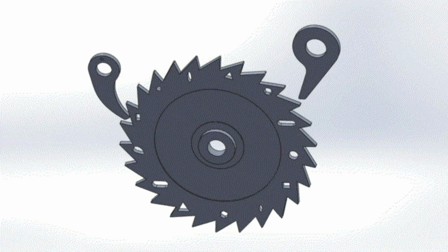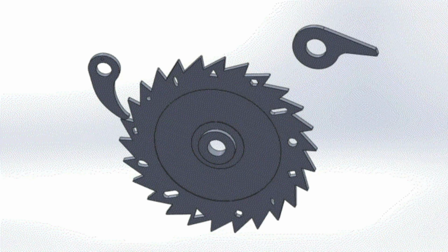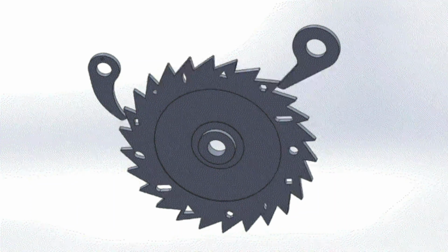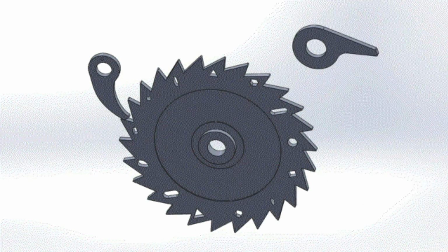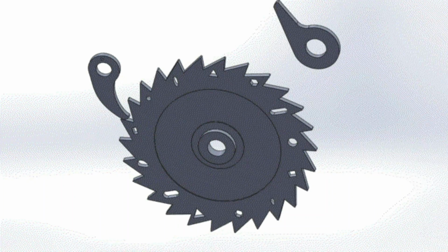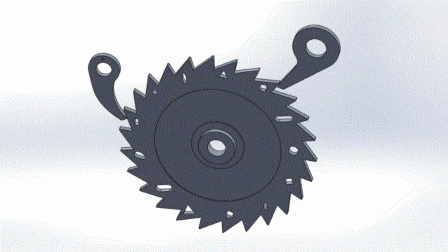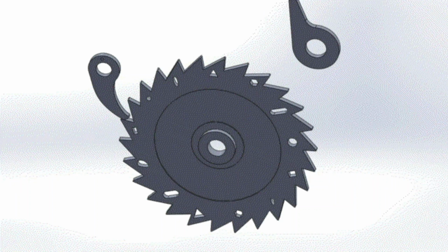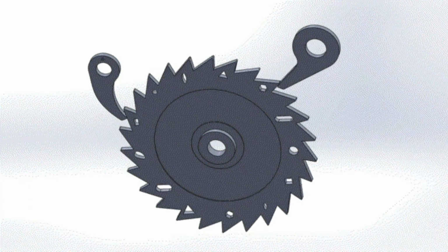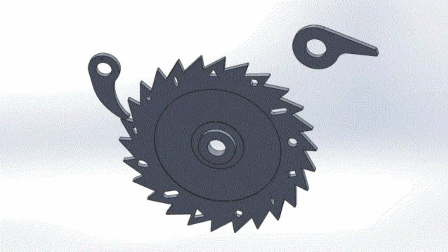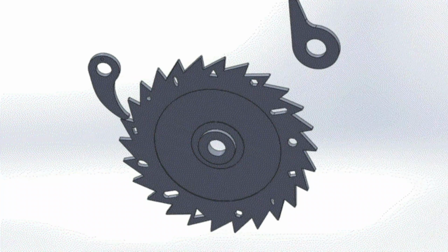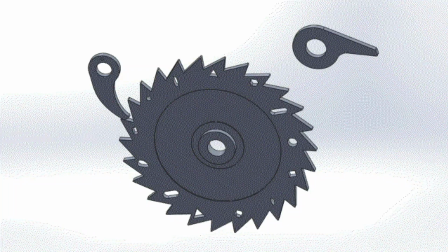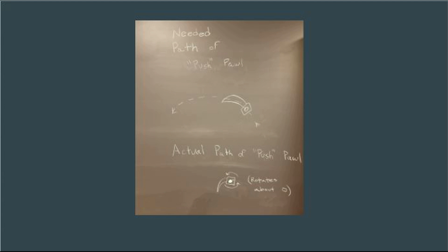In order to fix this problem, we decided to attach a shaft to our pinion gear. The other side of the shaft was connected to the push pawl. As the push pawl turned counterclockwise, it would push the ratchet in one direction. The stop pawl would be oriented so that it allows movement counterclockwise. Once the piston starts to move down, the push pawl would turn in the other direction and the stop pawl would prevent the ratchet from turning. This way, our ratchet gear only moves in one direction. Again, this only worked in theory.